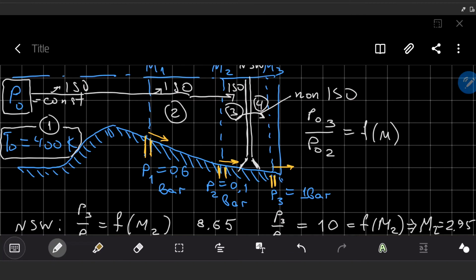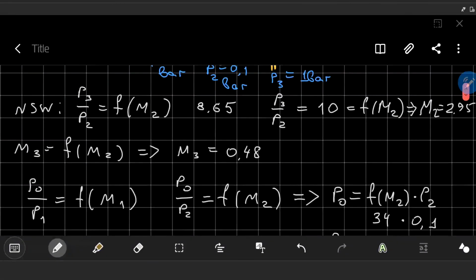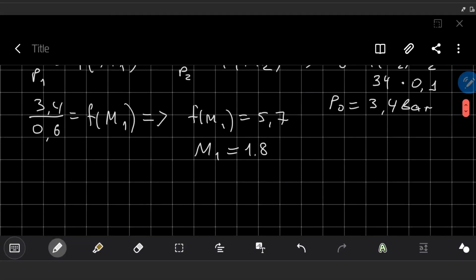Okay, it's this one. General formula is the following. Temperature stagnation divided by temperature at any arbitrary point would be equal to 1 plus (gamma minus 1) divided by 2 multiplied by Mach number squared. This is formula 840. Or inside Appendix A we also have the same relation.